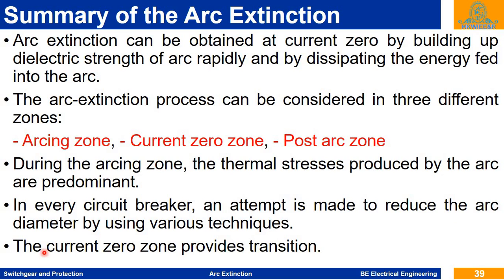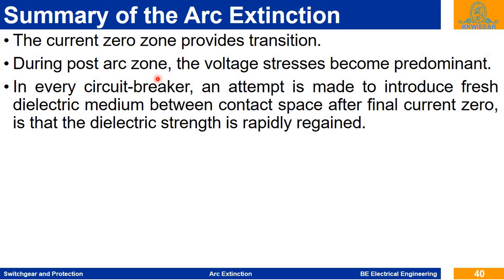The current zero zone provides the transition. During the post arc zone, the voltage stresses become predominant. In every circuit breaker, an attempt is made to introduce fresh dielectric medium between the contact space after final current zero, so that the dielectric strength is rapidly gained.